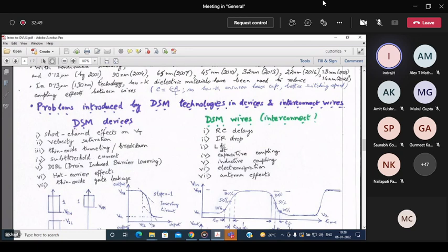That is talked about as sub-threshold current. What are the mechanisms? Okay, that we shall study later. Then DIBL, drain induced barrier lowering, also we shall just briefly touch. You cannot take a huge amount of time on these topics, but these are the effects of the deep submicron device. That means the barrier will become lower. Again, this will contribute to subthreshold current.